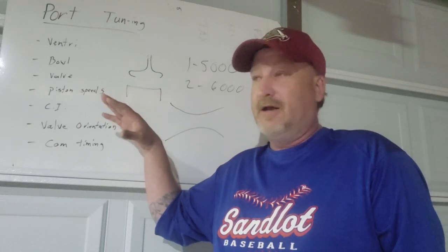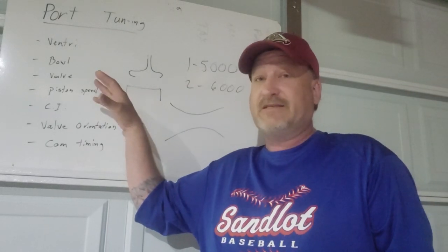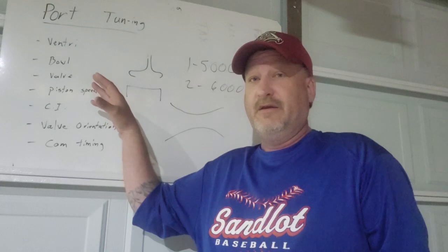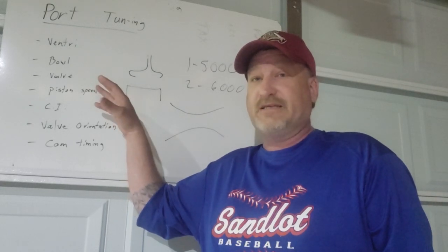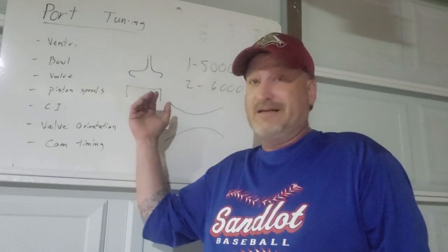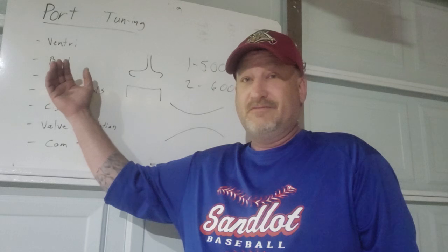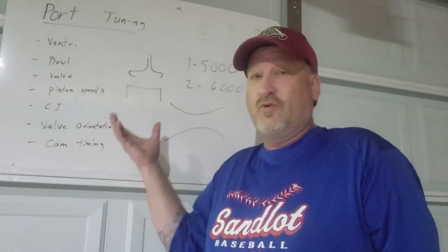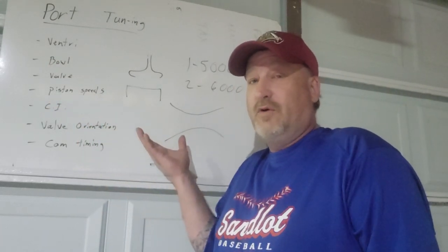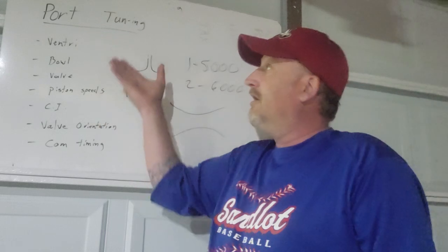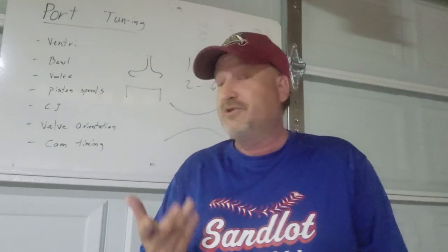Normally at lower RPMs, the exhaust gases can get out fairly quickly. But as RPMs increase, some of the air does not make it out the exhaust. So again, the ratio between intake port flow and exhaust port flow also contributes to port tuning.